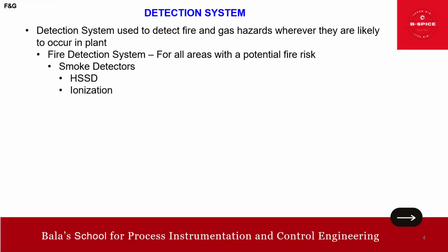An ionization smoke detector is a type of smoke alarm that uses ionization technology to detect smoke particles in the air. How it works actually: it has a radioactive material and an ionization process. It contains a small amount of radioactive material, typically americium-241, placed between two electrically charged plates. You know how it works?